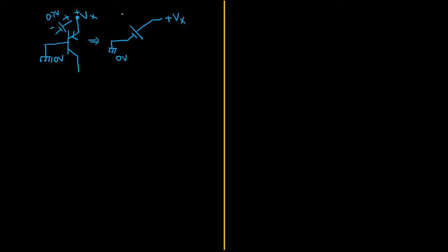Here we are having 0 voltage. This is minus plus 0.7 voltage. Simply apply a potential difference. While always finding the potential difference, see, the positive plate is connected with this node. The negative plate is connected with this node. So we have to subtract from the positive plate node to the negative plate node, because the subtraction should be higher potential point minus lower potential point.